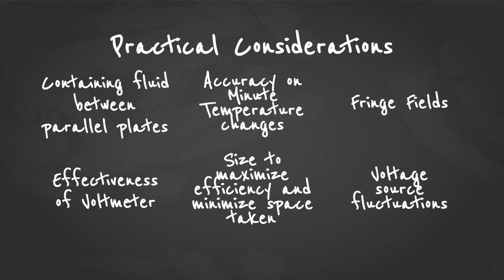But the problem is we have to take into consideration the water evaporating, the water leaking, and the water expanding. Because if the water expands, it could break the sensors and it can break the surrounding barrier. So we have to make sure we have a proper amount of fluid. We have to make sure that the barriers on the side do not increase the conductance of the parallel plates itself, and we have to make sure that the evaporation does not destroy any of the parts surrounding it. So containing the fluid between the parallel plates is probably going to be one of the bigger practical considerations.